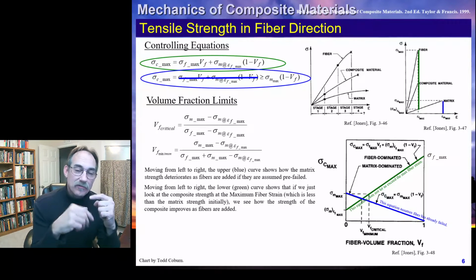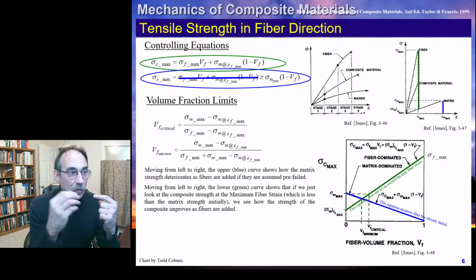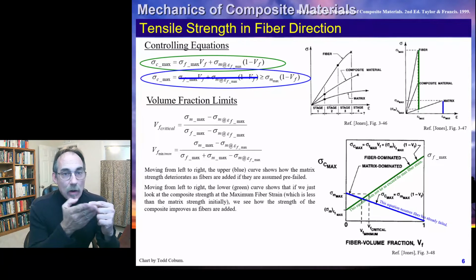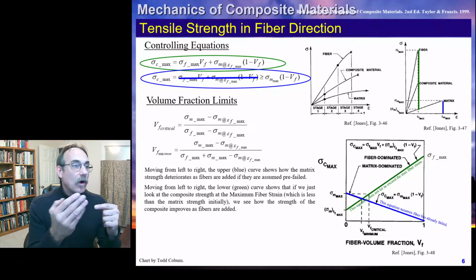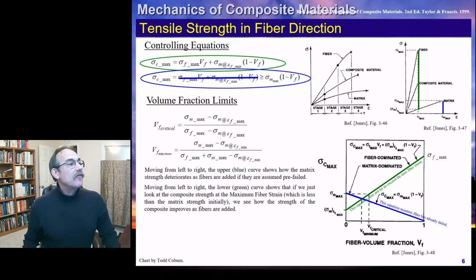So we've actually just thrown away part of the capability, for no reason, because there's actually no fiber. Now as we add fiber and go up this curve, we're getting more and more strength from it, and we see how the strength of the composite lamina improves as we add more and more fiber. That's the green curve. Okay.